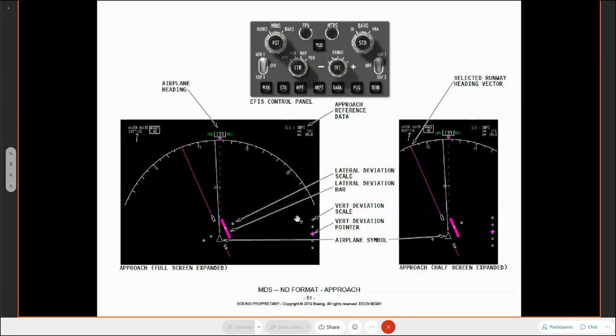The glide slope works in exactly the same way. As we intercept that glide slope beam, it becomes centralized. So as we come onto that beam, we hit it, and then we follow the beam down. Okay, the guidance down. We always fly towards the pointer. On this aircraft, as I say, you've got the option for GLS as well, but the indications are the same.